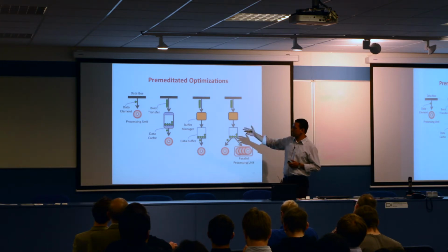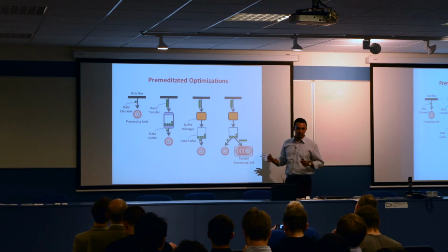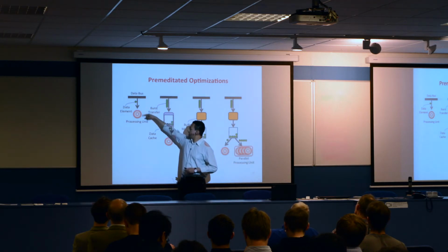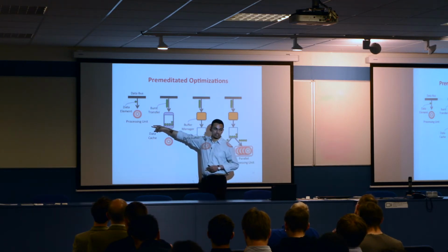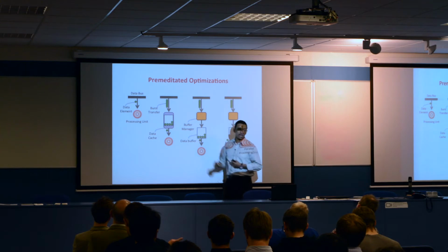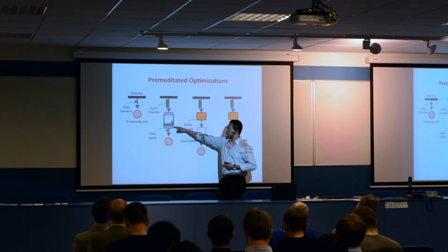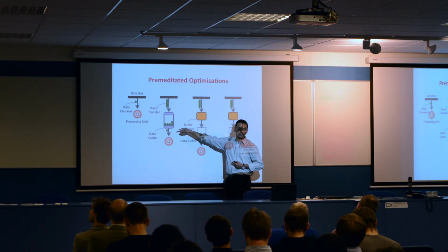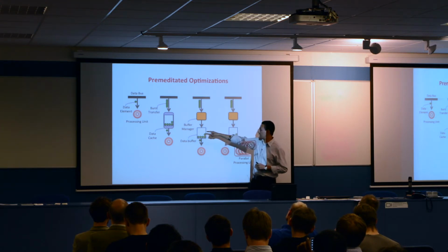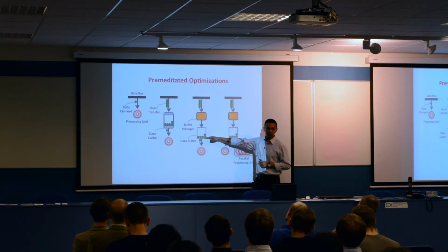Let's consider a case of a single pattern where it reads elements from a data bus. If I normally use a high-level synthesis tool without any optimization, I would probably get one of those units, essentially one unit taking each element at a time and producing the output result. But if I know that I have data reuse happening, then I can explicitly instantiate a cache here. The cache will make sure that the accesses can be done in burst transfers, and I can efficiently use the data from the cache. But if I knew the data access pattern, probably a cache is overkill. Maybe I can just put in a buffer manager and use a local buffer.